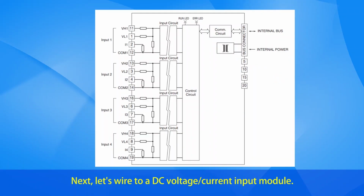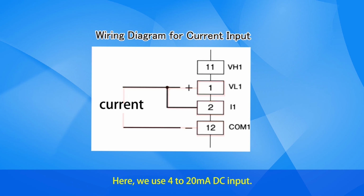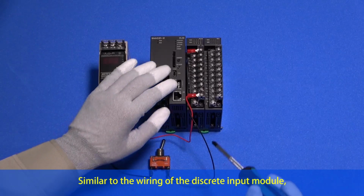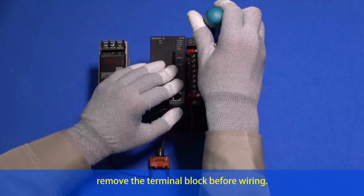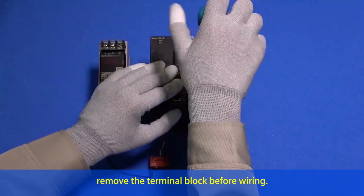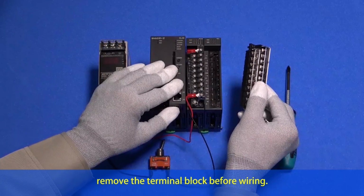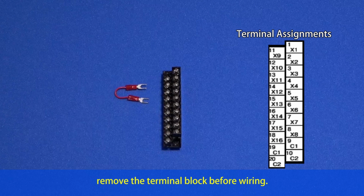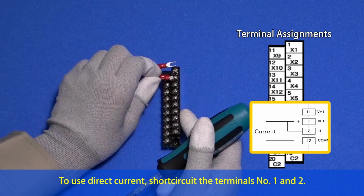Next, let's wire to a DC voltage current input module. Here, we use 4 to 20 mA DC input. Similar to the wiring of the discrete input module, remove the terminal block before wiring. To use direct current, short-circuit the terminals number 1 and 2.